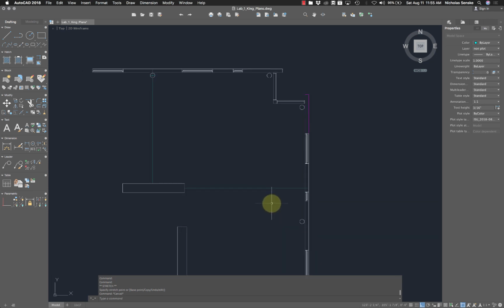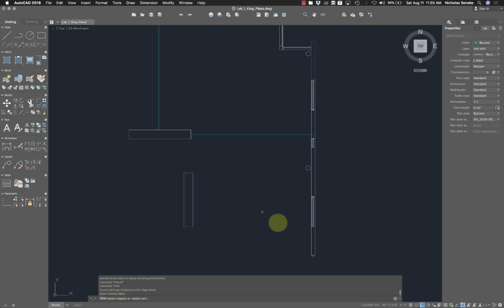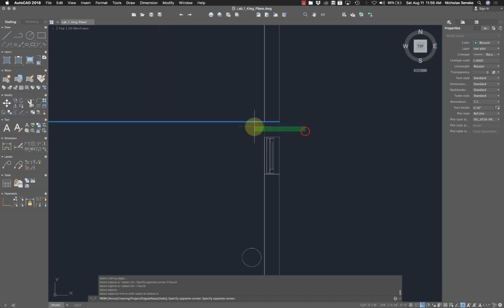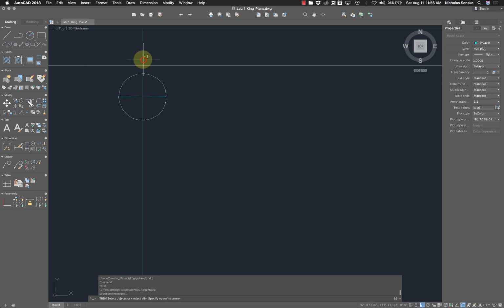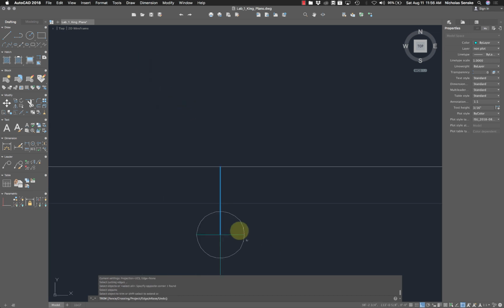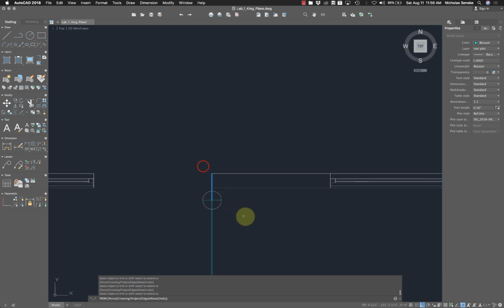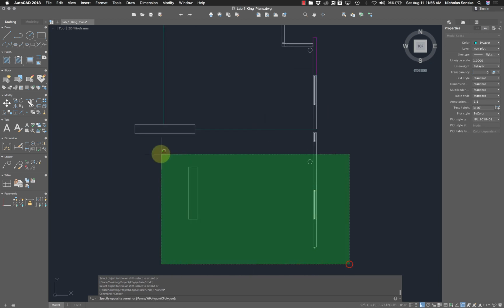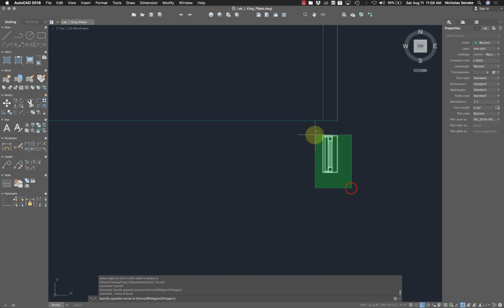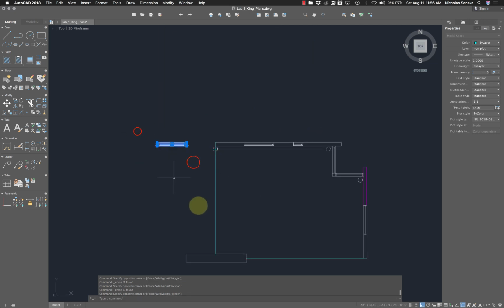I'm going to use this to trim the edges. Trimming is another command that's really useful. So trim is just, if I have a line, it says select objects, so I'm going to select the trimming object. And then when I'm done with the objects I'm using to trim, I press enter. And then anything that I sweep gets cut, basically. So I'm going to do that again up here, and practice this. Okay, so I've selected it. Now I can just cut these, and you can cut them by clicking, or you can cut them by dragging. Dragging is often really useful. And then I can go ahead and delete all these. And this method is really precise and useful.